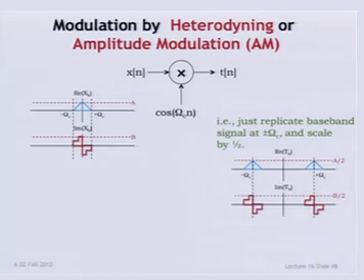All right, so just to think spectrally, we had a simplified version of this picture last time, but let's first assume that this signal has some spectrum, which is shown by a cartoon here. I'm assuming a real signal. So we know that the spectrum has a real part that's even and an imaginary part that's odd, and that's what's shown for you here in this figure. Okay, so we're going to track the spectrum of the signal by tracking the real and imaginary parts separately, because the spectrum is in general a complex function of frequency.